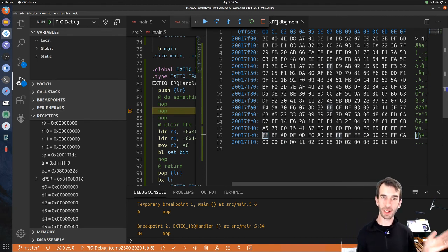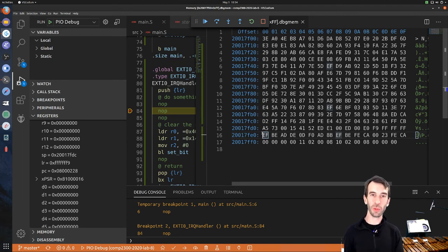So how does this affect your assumptions? Well, thankfully, when we call a handler or an interrupt request gets called, we're not relying on some other colleague or yourself to have written your function correctly so that it packs up all of the context that you might want to save. It's built into the CPU to do that, so you don't have to worry about those caller save registers being saved and restored. So that all works perfectly. It's designed as part of the CPU.